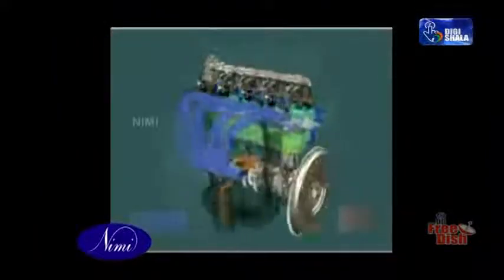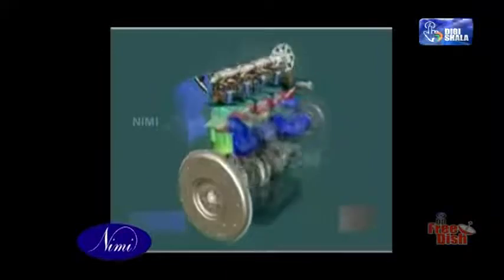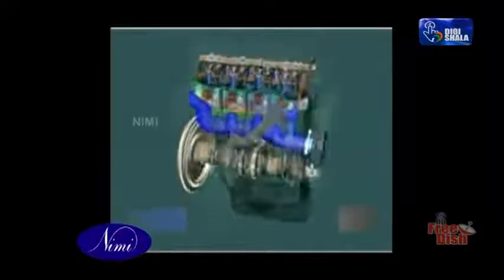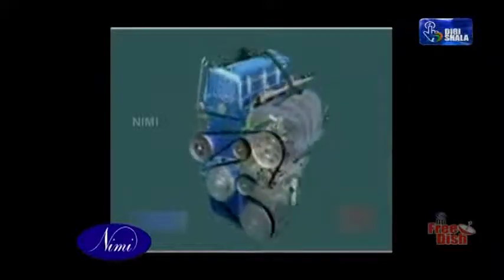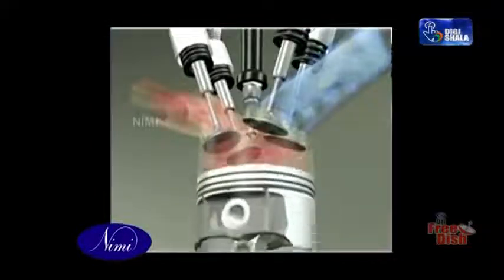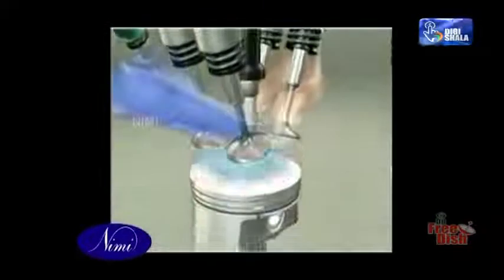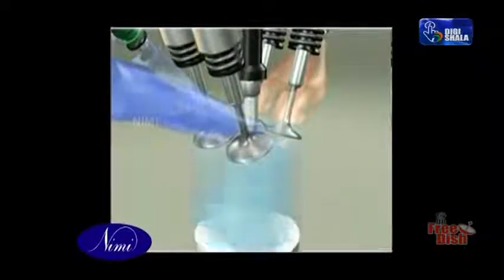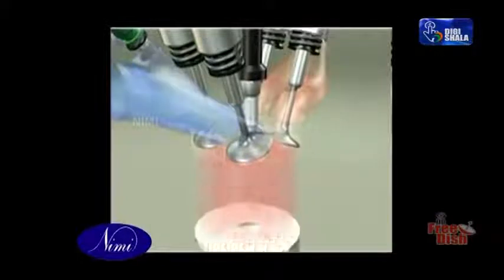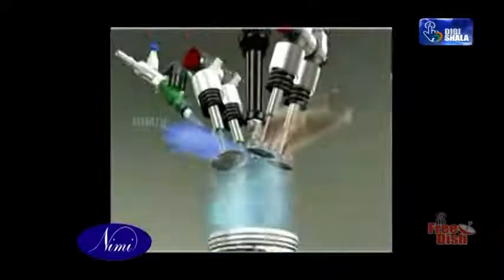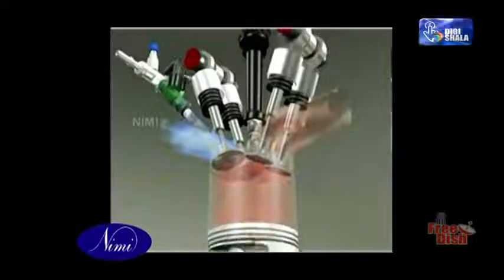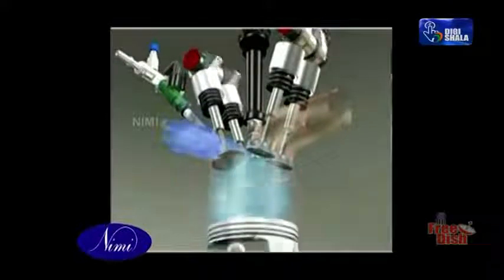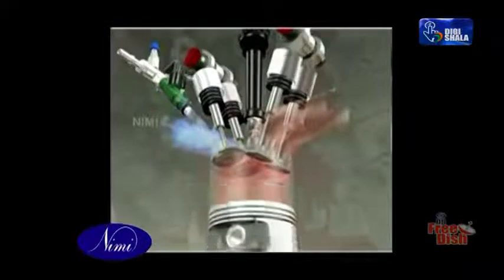Some form of cooling must be provided to take away the heat from the cylinder and working parts of an engine. This heat comes from combustion of the fuel and friction between rubbing parts. An uncooled engine would result in seizure of working parts due to heat expansion, excessive wear, the oil would be burned, and pre-ignition of the petrol-air mixture. This means that the mixture would be ignited before time by some red-hot particle in the combustion chamber.